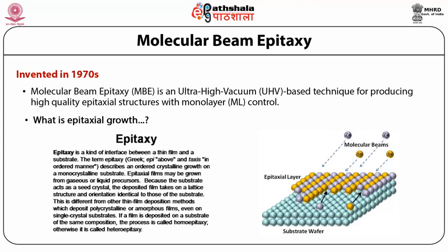Epitaxy is a kind of interface between a thin film and a substrate. The term epitaxy describes an ordered crystalline growth on a monocrystalline substrate. Epitaxial films may be grown from gaseous or liquid precursors.